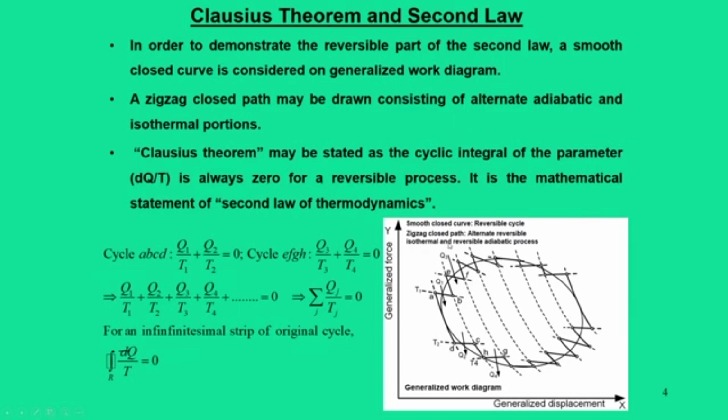The heat is nothing but the heat rejected by a reversible engine. Essentially, the reversible engine receives dq1 amount of heat at T1, and the irreversible engine produces dW amount of work. So, reversible and irreversible, this entire thing is the system.